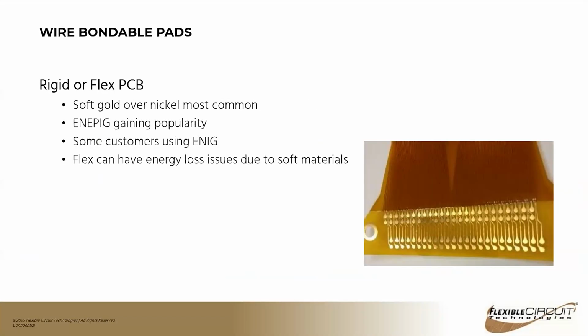And then wire bondable pads. It seemed like this was really going to take off. It seems like it's kind of stalled out where we see it, but not a ton of it. It's certainly not as common as ZIF. For this technology, the big thing is to remember your final finish. So most commonly, it would be soft gold over nickel. ENEPIG is gaining popularity, and then we've actually seen some customers use ENIG. One thing to keep in mind when you're using this is with a flex circuit, these materials will compress, so you are going to see some mechanical energy loss when you go to use it.